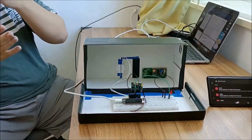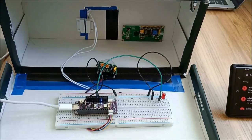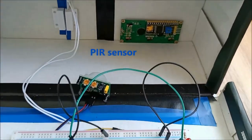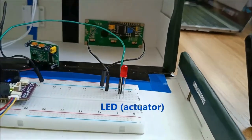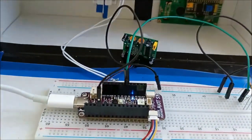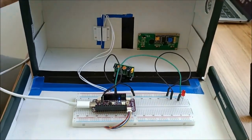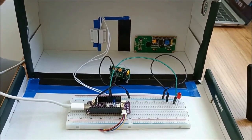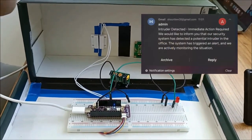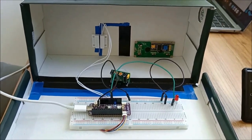Now let me talk about the circuit design of our project. As you can see here, we are using the AIoT S3 board as our main board, and we have a PIR motion sensor here, which will detect the motion whenever the door is open. We also have an LED and a buzzer to act as an alert whenever the motion is detected. Last but not least, all of this is connected to the V1 platform so that it can send the data to the platform for analysis and also send an email notification to the owner whenever the motion is detected. Now let me demo how it works.